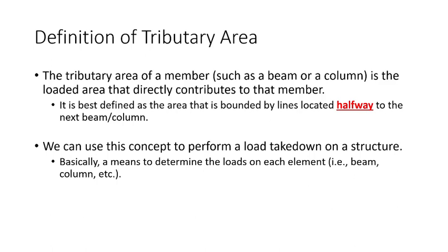You only have this much footprint on the ground, so it is advantageous to get as many stories in the building. Let's say a normal one-way slab system is only going to be 18 inches deep. A two-way slab might be 12 inches deep. You think, well, that's only 6 inches. Well, add that up over 30 stories, and you get another story in the building.